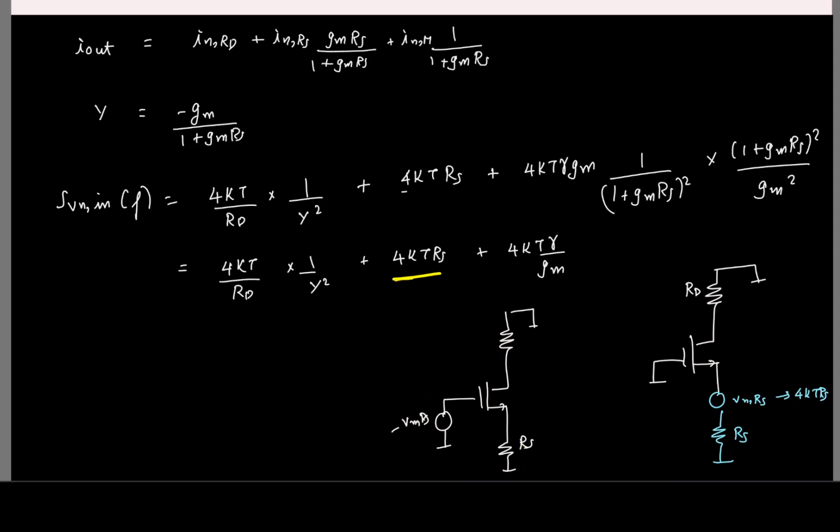Okay. Now a similar thing happens for the transistor. So for that, let's understand this. See, if you have a MOSFET, the way we have modeled the noise is using a parallel current source like this, right? Say, let's say INM. And we know for a fact that if there is any noise at the output, we can refer it back to the input and model it as though it is coming from a voltage source and a current source. Now here the input is the gate of the MOSFET. So how many noise sources you need to model the output noise? One, which is just voltage.